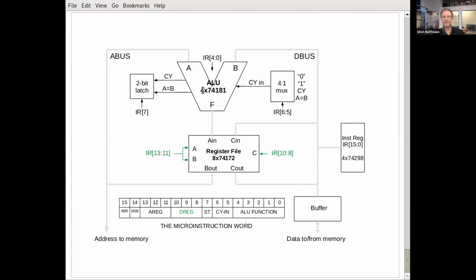That makes sense. Yeah, the register file and the buffer can both be tri-stated. And the question here is, is it worth adding logic to prevent that from happening? And maybe it is. We actually have 4 signals on the board. There's memory read, which goes to the memory, memory write, which goes to the memory, read enable C, which is to enable that output on the register file, and write enable C, which means that when data is available on the data bus, at the end of the cycle, that will get written into the C register.